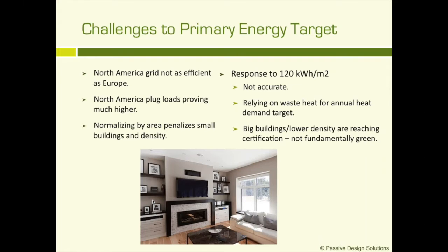One was about an 8,000 square foot office building, and one was about a 1,200 square foot house. The 1,200 square foot house had a final ACH of 0.66, and it was one of our early projects, and we thought by putting in drywall we'd squeeze out that last little bit with an air tightness strategy and drywall, but we did not reach that target. The builder was celebrating really strongly with his 0.37 air changes per hour in the commercial building.